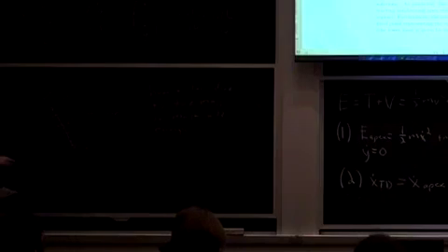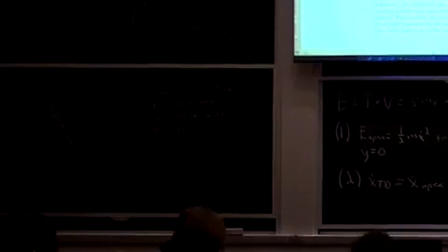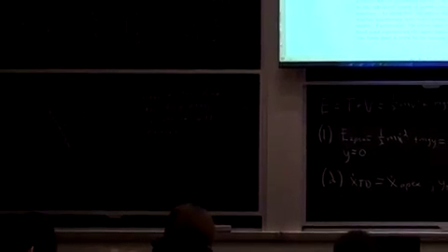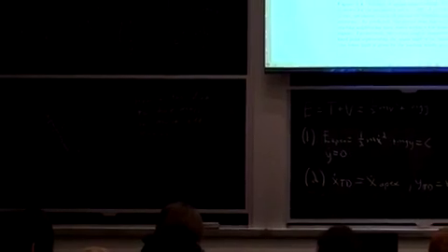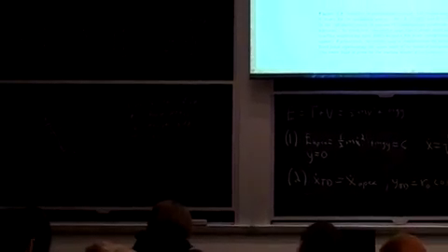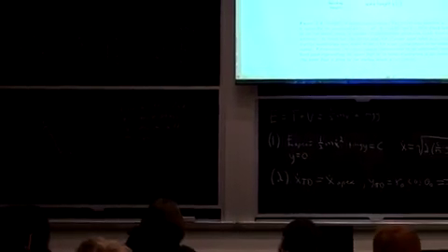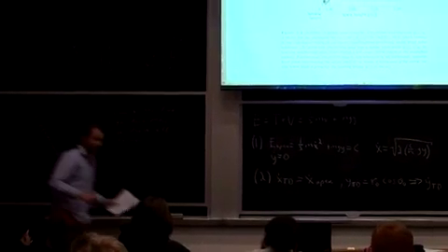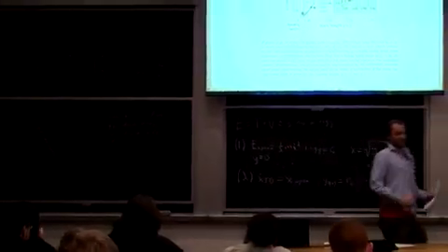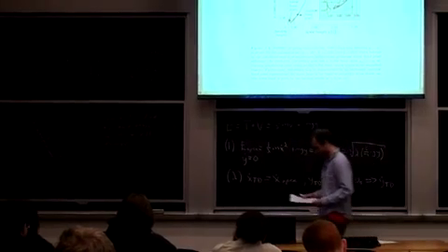And you actually can get similar stability properties to the SLIP model. You can get these when you simulate it. You can find the same sort of stable fixed point, unstable fixed point kind of behavior. And so this is all what we've been talking about. Sort of the image we have is this sagittal plane dynamics, right? The sagittal plane is this plane, and so this sort of idea of running through like that, right? Getting a little bit of aerial phase so it'll look less ridiculous.